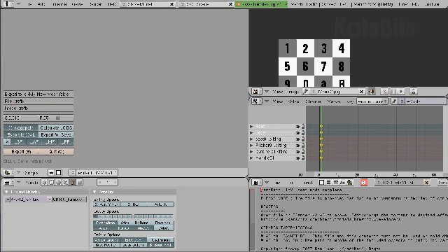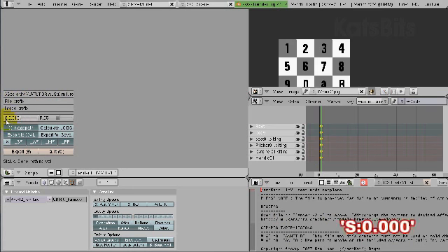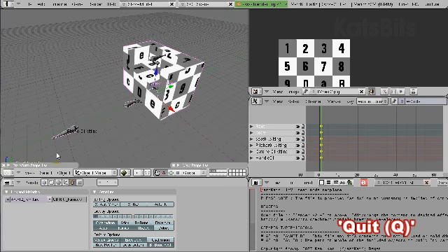Now we need to make sure, copy paste the folder location or manually type the location. Make sure that S, the scale, is 0. Everything else needs to be left at default, and just click the export button. Done. It will tell you quit, and that's the mesh exported.